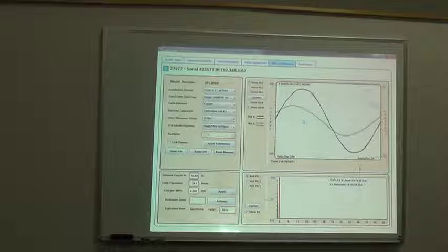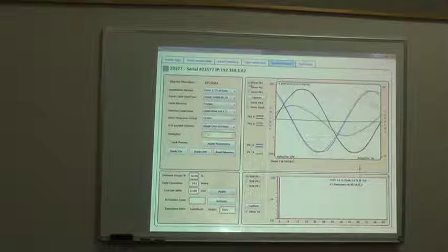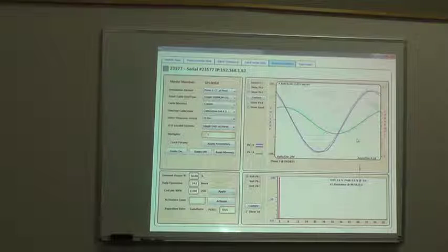There is a major benefit to that, and because of that, I'm going to put 3 more check marks here, so you can only show the simulated version instead of the actual one. Because the simulated version has one benefit. In this case, it's easy because they look like sine waves. But in this case, okay, if the current is distorted that much, you really don't know where the peak values are, okay? Because the peak values tell you basically what the real power factor is. This is the real power factor as opposed to what we measure.